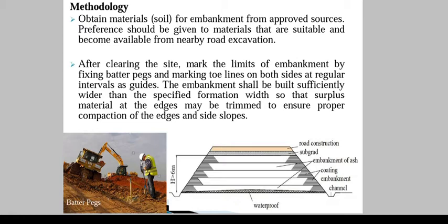And later we have discussed the construction steps. The area needs to be cleaned and freed from vegetation or organic substances, then that needs to be compacted. Then we'll be dumping the good quality soil, muram, or construction embankment material, and that needs to be compacted at our desired OMC, that is, compacted in layers.